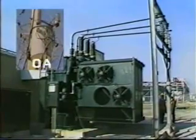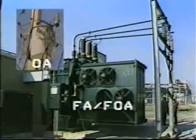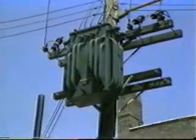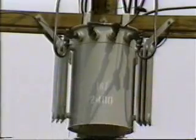Now, the cooling method used on distribution transformers is the oil-to-air or self-cooling method. This is in contrast to substation transformers, which often used forced air or forced oil and air cooling. On large kVA-rated distribution transformers, say 100 kVA and above, radiators are often installed on the tank to improve the heat transfer capability. Instead of the radiators shown here, cooling fins may be attached to increase the area of the tank.